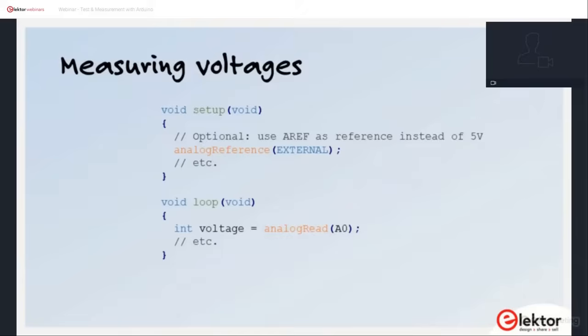The Arduino UNO has 6 analog inputs that will work without configuring them first. You don't have to do this because Arduino does it for you. You can read the analog inputs with the Arduino function analogRead. This will return a 10-bit value from 0 to 1023, which covers the input range from 0 volts up to the ADC's reference voltage minus 1 bit.